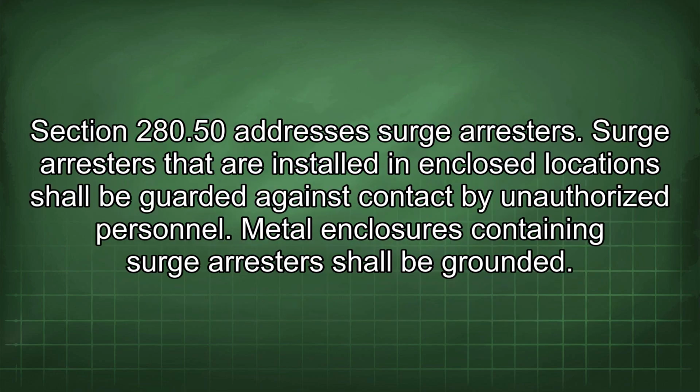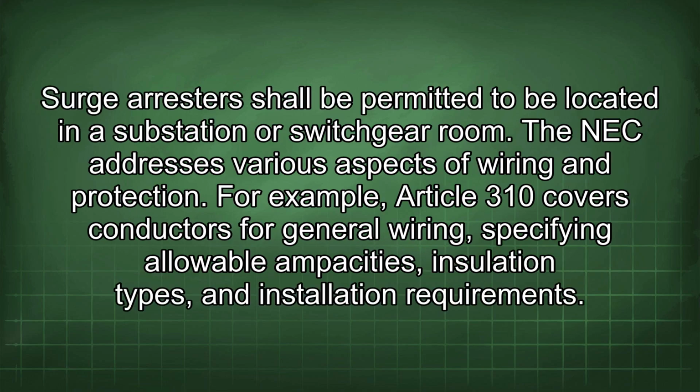Section 280.50 addresses surge arresters. Surge arresters that are installed in enclosed locations shall be guarded against contact by unauthorized personnel. Metal enclosures containing surge arresters shall be grounded. Surge arresters shall be permitted to be located in a substation or switchgear room.